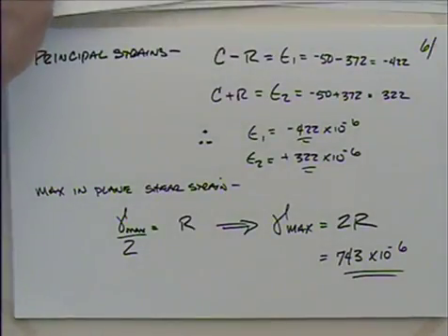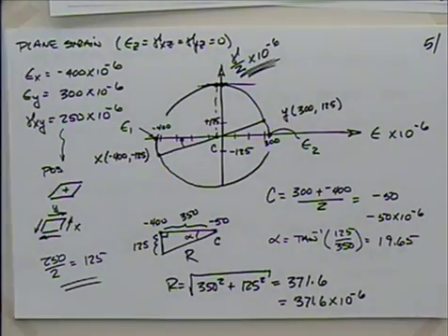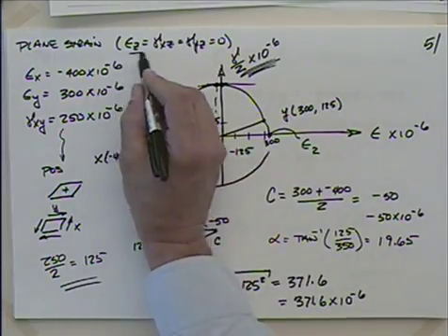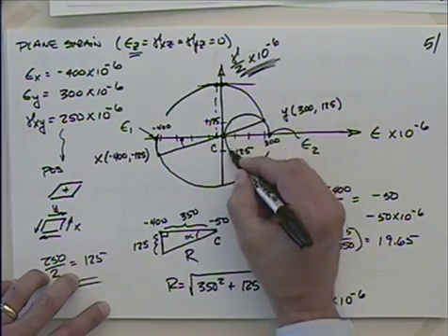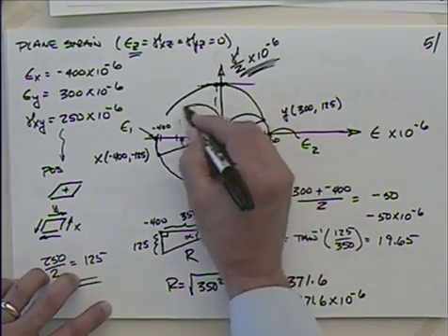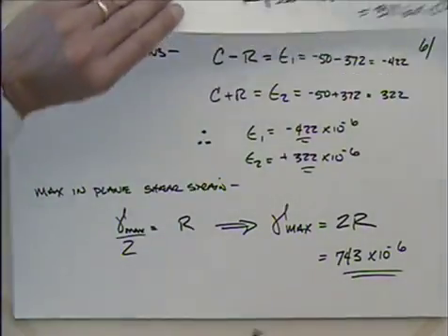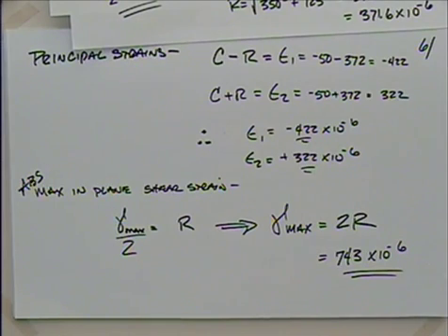Okay. Now, with the stress circle, we were always talking about, well, let's see if that's maximum in plane or is that absolute maximum. If we're looking at a circle here where epsilon z is equal to 0, there's epsilon z, and we actually have these smaller circles in here like this, don't we? So this is also what? Absolute maximum, isn't it? Because we were dealing with the biggest circle already, weren't we?